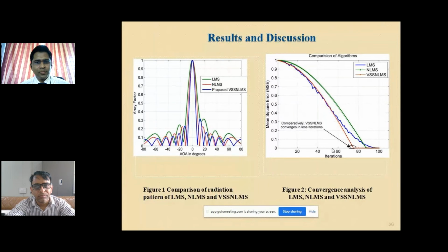They are called minor lobes or the side lobes. The side lobes are of no interest. In a smart antenna, if the number of antennas is increased, for example, 10 antennas replaced by 64 antennas, as in 5G, these side lobes will automatically disappear. Only one major lobe will appear in the user direction.